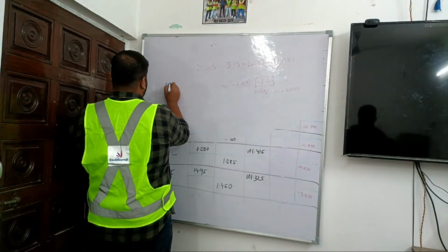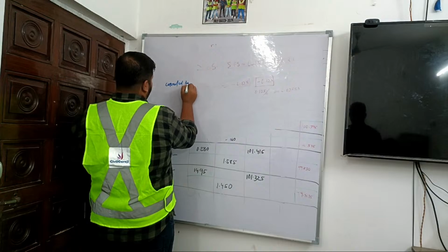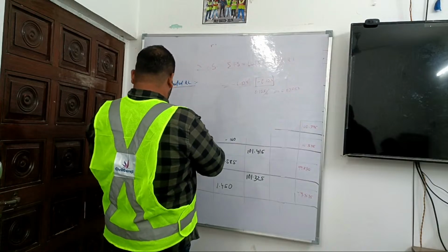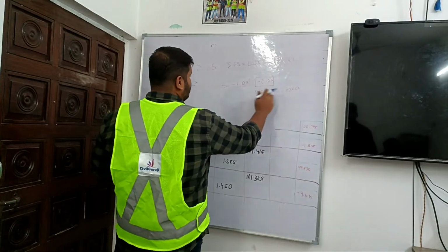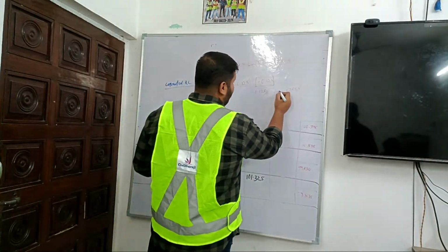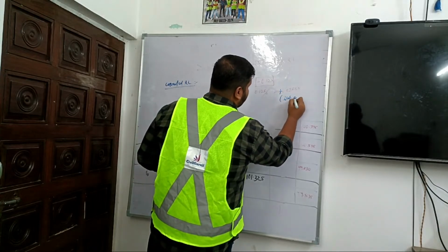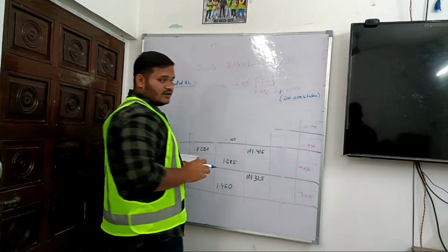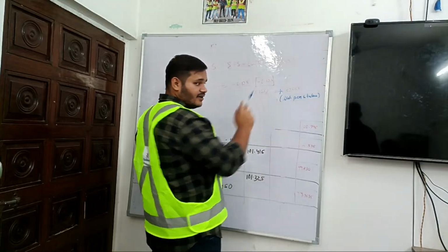Now let's see the corrected RL table. Now we have to add a column there. Okay, this value comes to be minus. So if the correction value is negative, then we have to add the distribution per station value. If we get the value in negative, we have to take the value as positive. Means we have to add this value to the found RL.